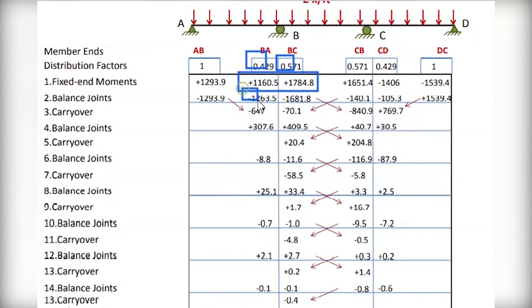Now you shall have the value here, and the same at this point after repeating the procedure. After times by -1, you shall have this point. After this, do the carryover. The carryover factor, as you did before, is half of the value. For example, the value here times by half gives this one, 600 from this one, and this value here times by half gives this one, and the same for the other values.